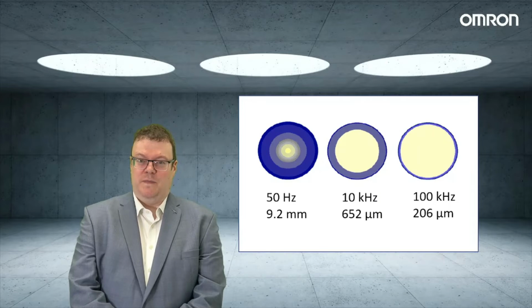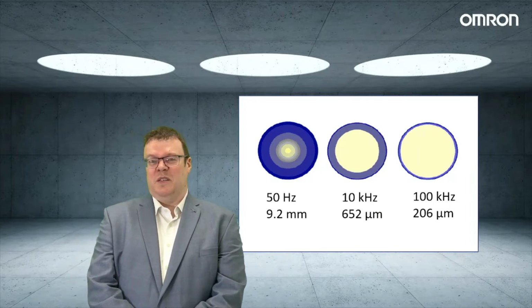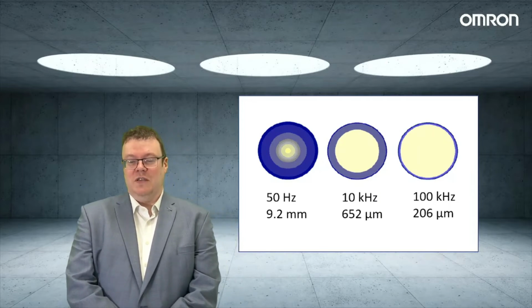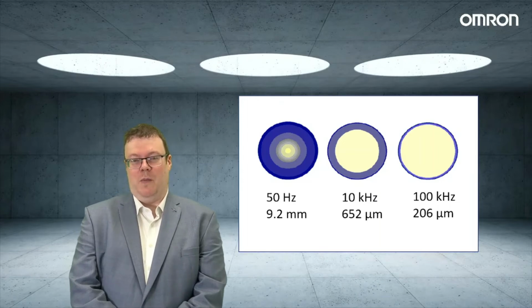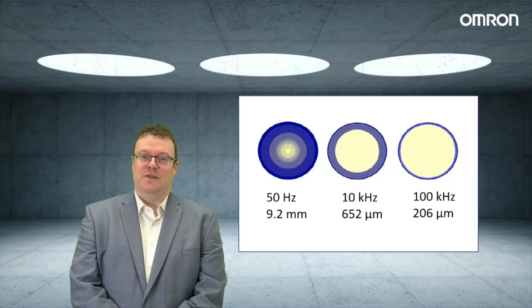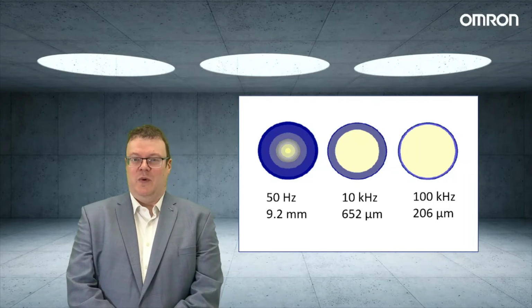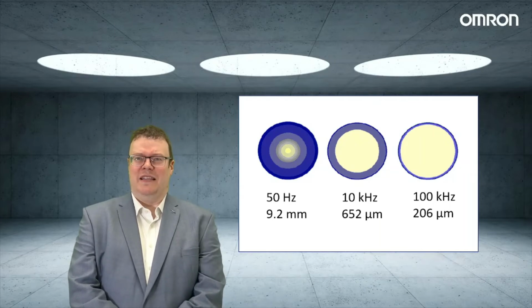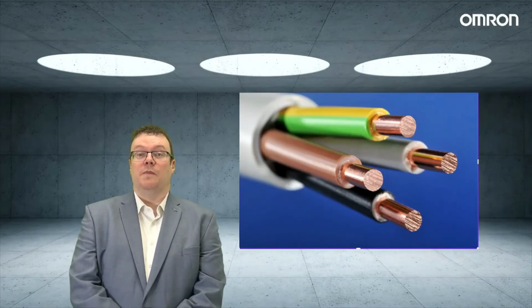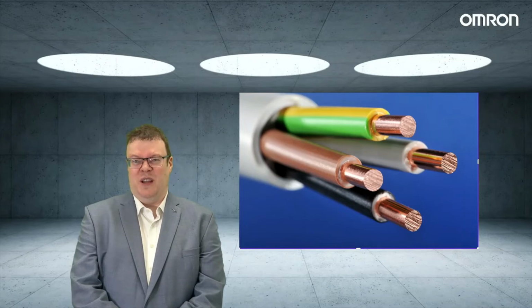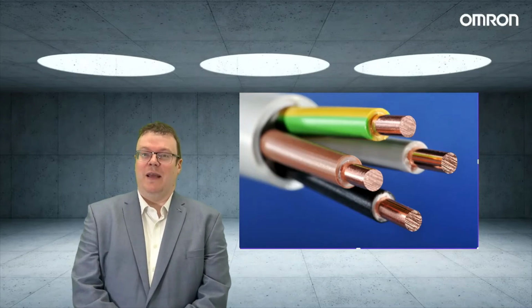Now, the reason why this is important in control panels is if you've seen some of our earlier tech talks, we speak about harmonic distortion and the high frequency noise that's generated by inverter drives. In these situations, we are talking about frequencies that can be in the 10s or above kilohertz. So, essentially, for low voltage and mains and DC, solid cables will suffice.